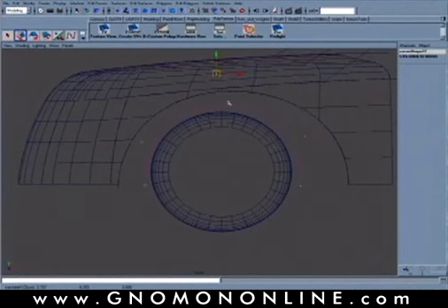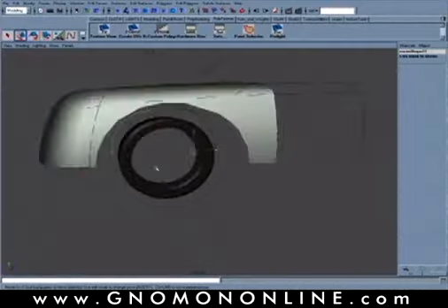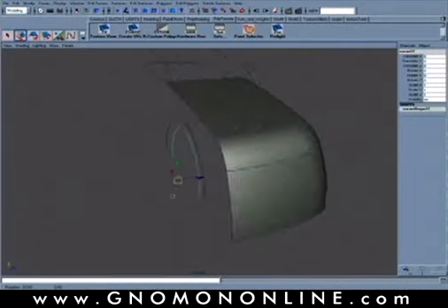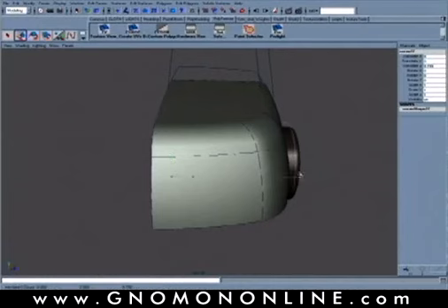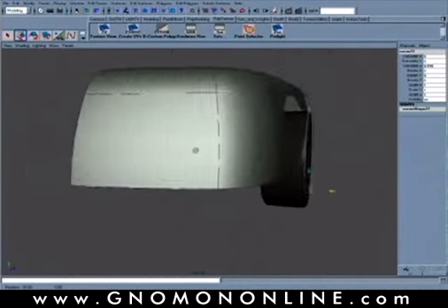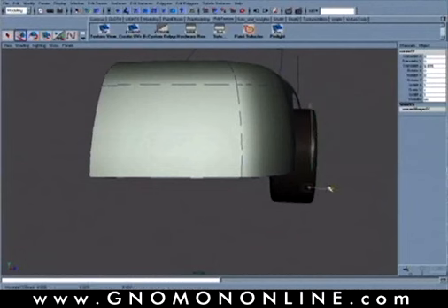Okay, so this is just going to be encompassing the boundary of where that actual wheel arch is going to exist here. Notice that it's going to be offset or inset from the other surface that we had trimmed out. Coming into our perspective mode, you can see that that was drawn at the center line. So I'm going to take this curve and translate it out so that it's fitting pretty much right over the tire. And this is basically a design preference as far as how far out you're going to want that.